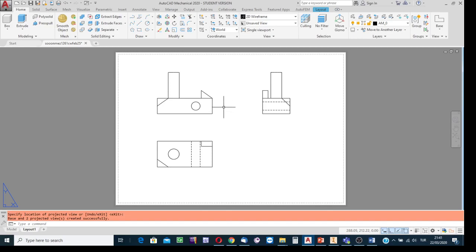And then the symmetry axis. You know, if over a projection there is a full circle or semicircle or full ellipse or semi-ellipse, then horizontal and vertical symmetry axes are needed to show. If there is a revolved feature or the object is a revolved object entirely, then on the lateral side view of the revolved feature or revolved body, the longitudinal axis is a must to show. Okay.